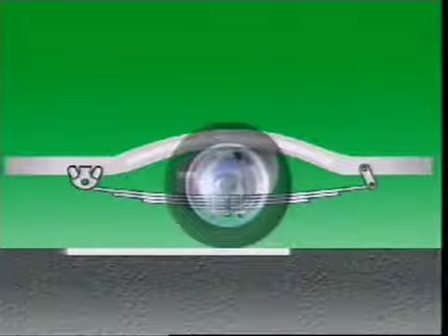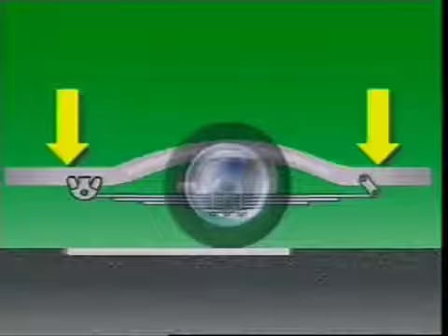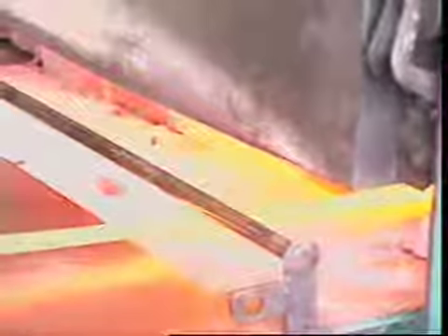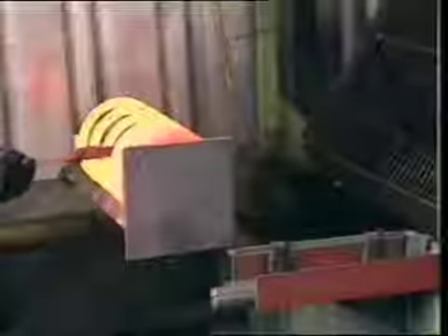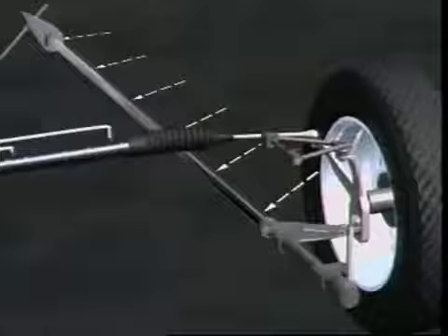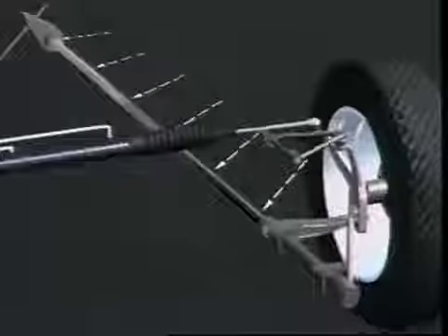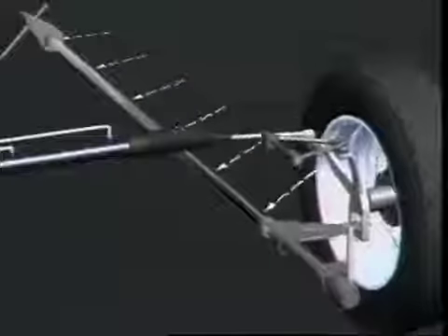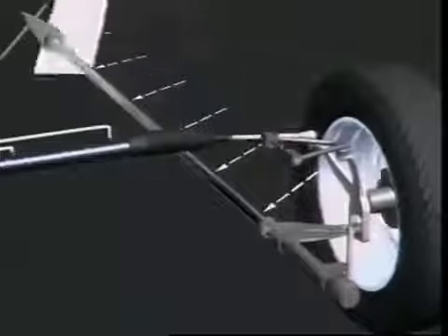Leaf springs are normally semi-elliptical, and they absorb the applied force by flattening out under load. Coil springs are formed in a spiral from a single steel rod and absorb the force of impact by twisting. Torsion bars are held rigid at one end and twist around their center as the suspension arm is deflected. They all return to their original shape when the deflecting force is removed.